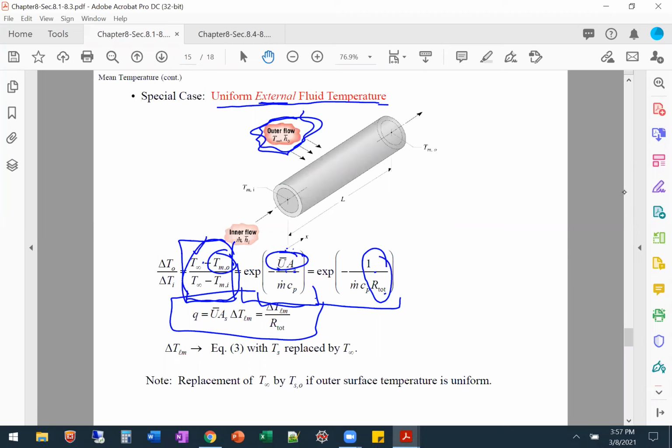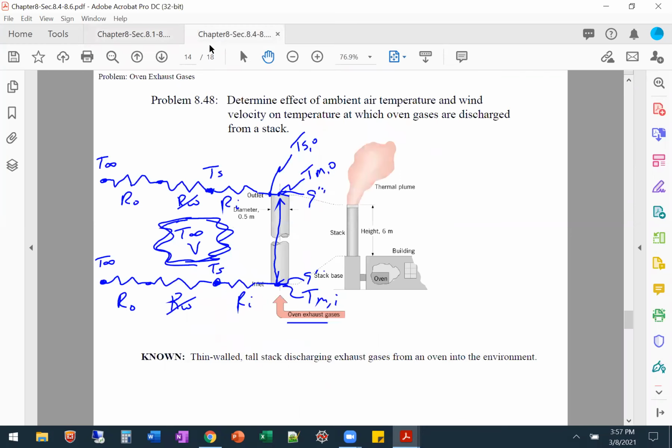So we have T infinity, we have the inlet temperature, mass flow rate was given, so we just need geometry, the surface area that convection is occurring on. We need our specific heat, so again, properties lookup. Okay. So that's to get the outlet gas temperature.